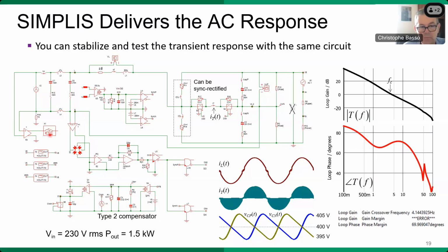I was able to build a complete T-type PFC here. The source is still active. That's the beauty here. You can see the AC source is actually biasing the PFC. So this guy operates as if it was wired in the lab. And then with this, what we call the periodic operating point, SIMPLIS is going to determine what the steady state is. It means everything is stable and the transient period is over. All average currents in capacitors are approaching zero at the pico resolution level, and the same for the average voltage across any inductor.